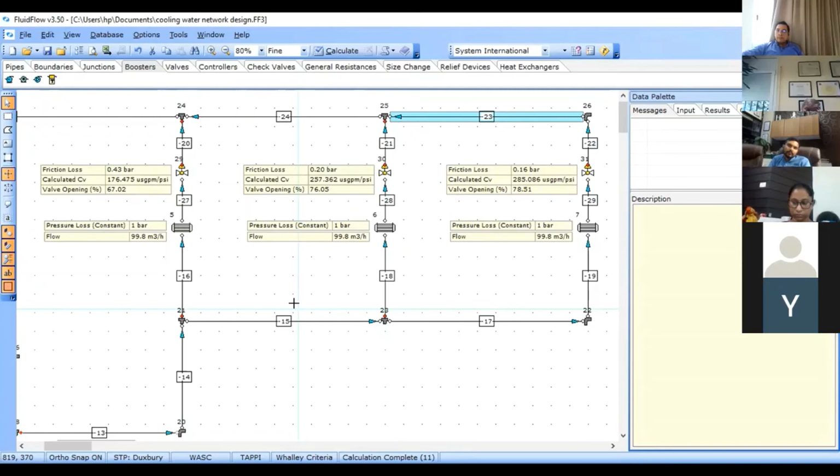It's once in a while now. It's a project. It's something you put at the installation, after which it's just maintenance. Correct. So it's okay. All right. See, in the project we had done for Bharat Oman Refinery, they didn't have any globe valve for throttling purpose. They had the gate valve for isolation. The gate valves are not fit for throttling. So that's why they could not maintain. They wanted to reduce or increase, but it was not really happening. Okay.